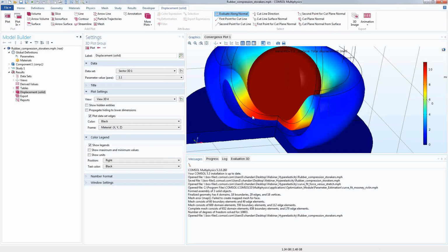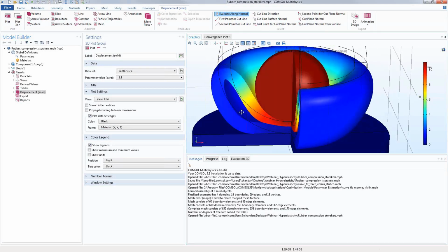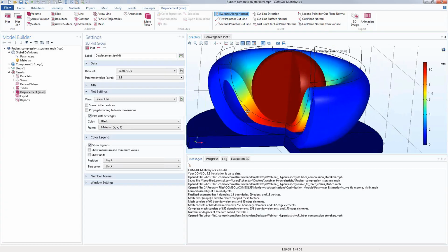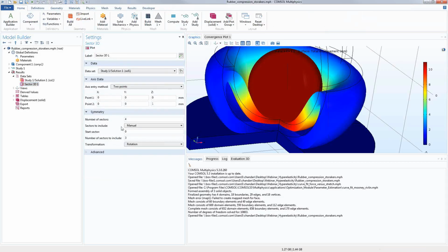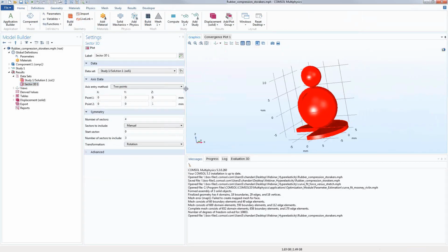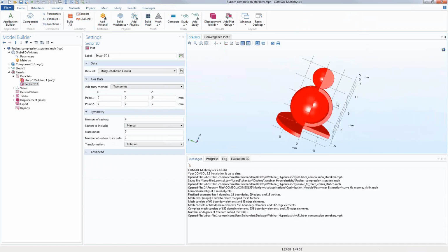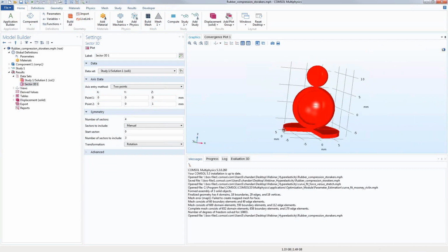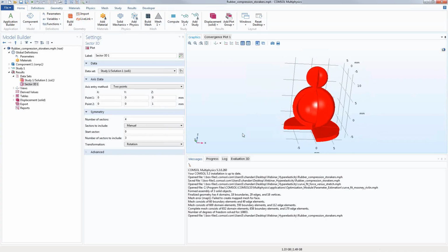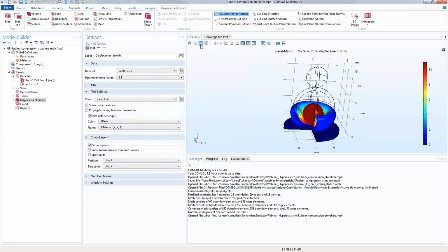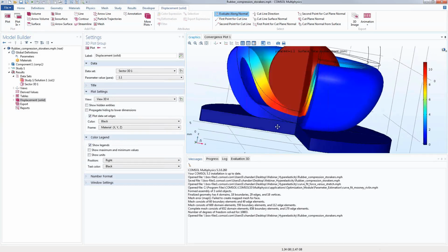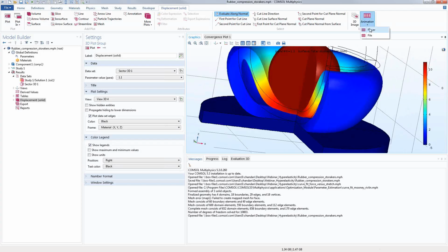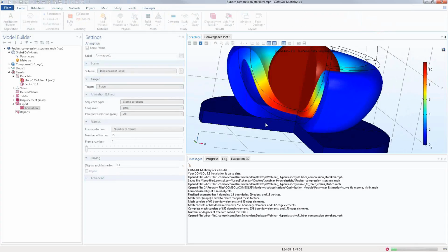So what we are seeing here is the displacement plotted for a sector of the geometry where I have taken out one part of the geometry. So I've created a data set that allows you to plot on this geometry, where I have removed one sector of my full geometry. Right? I've taken 3/4 of my entire geometry. That's what I'm showing just for clarity's sake. And you can see here, finally, at the last parameter value, the foam has compressed entirely, and we could probably animate this. So let's animate this with a player and see how this compression proceeds.